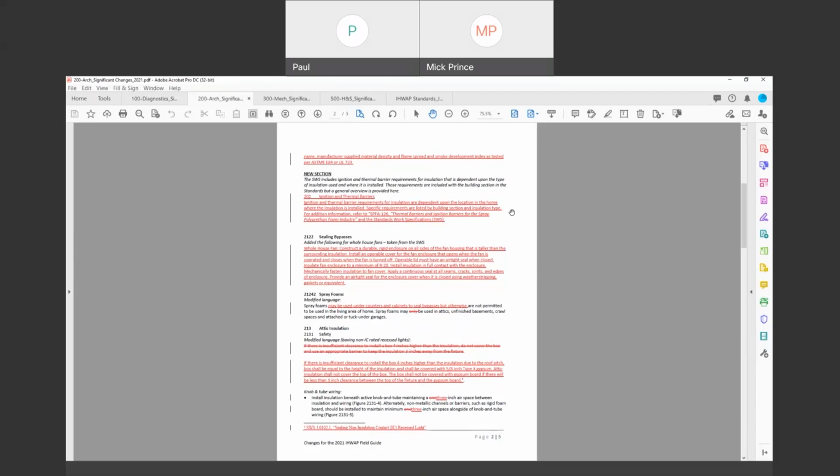There's a wonderful document, noted there, SPFA 126, that spells out where thermal and ignition barriers are required and the types of materials that would encompass a thermal or ignition barrier. I know some agencies are using this intumescent paint coating. They just spray it over the spray foam, and that works as an ignition barrier.